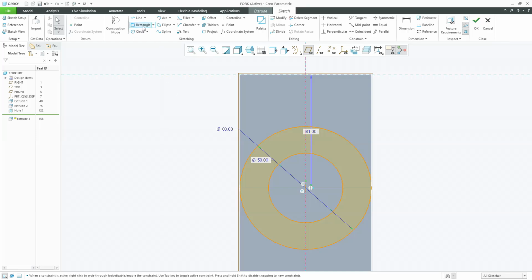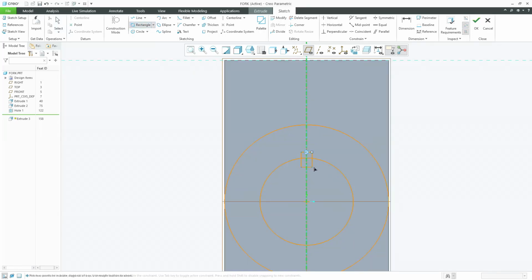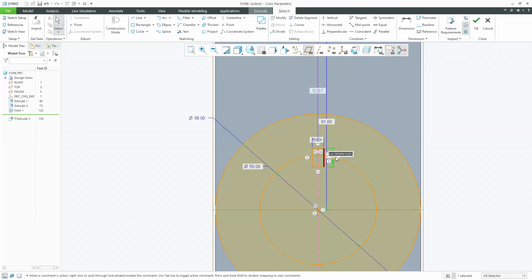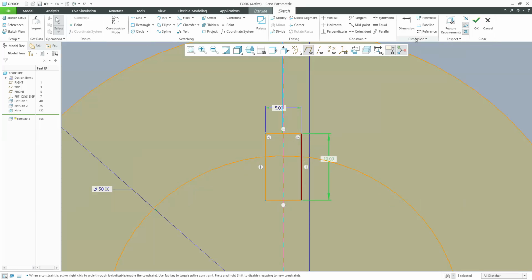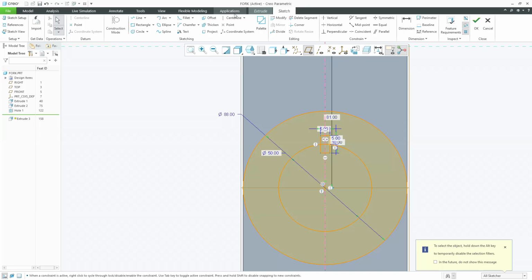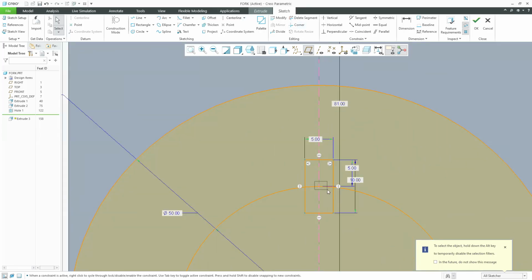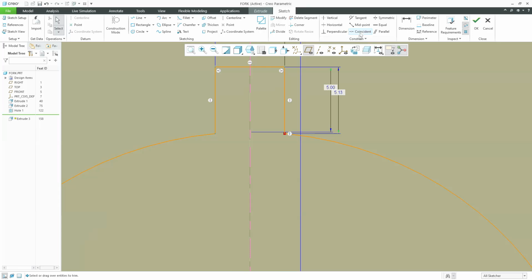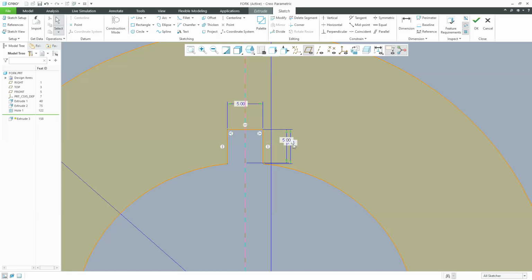So I'm going to select a rectangle here, adding a rectangle which is symmetric in the way. This distance would be 5, and this distance would be 10, and I need the distance from here to this one as 5. Now I'm going to delete the unwanted lines, delete segment, delete these lines. I'm going to corner these connecting points. So I hope this would be fine.